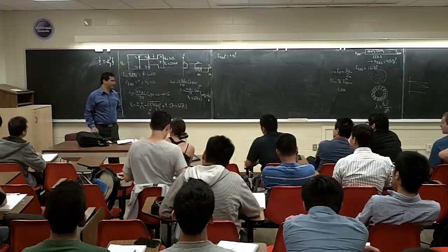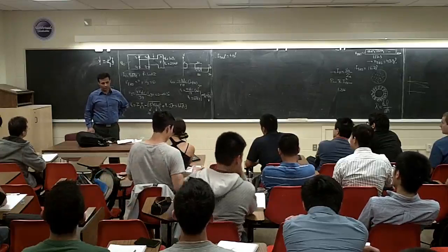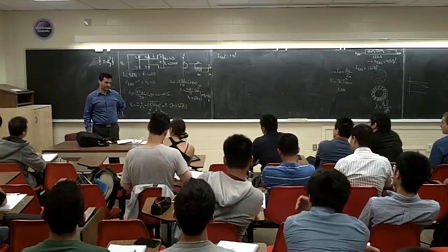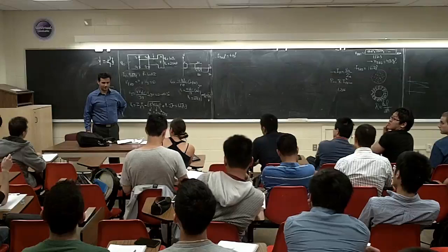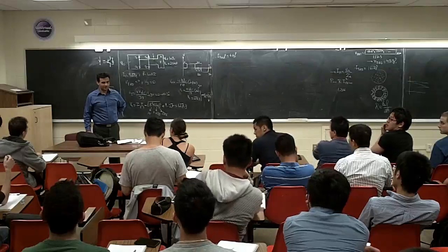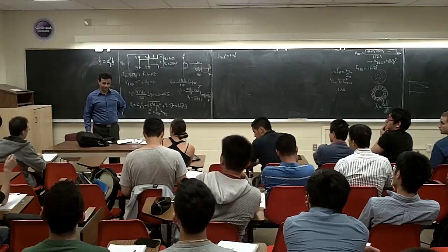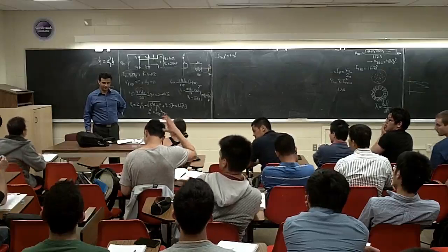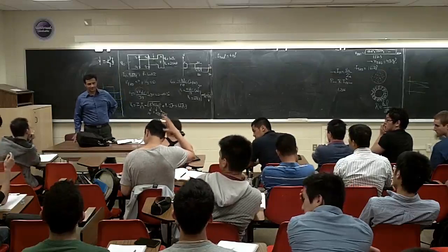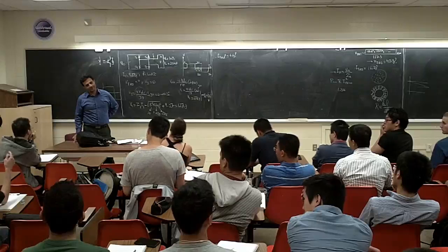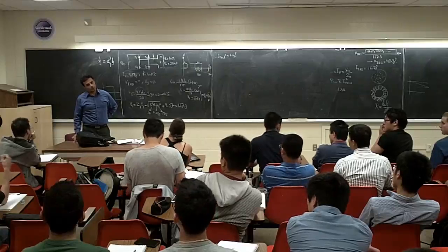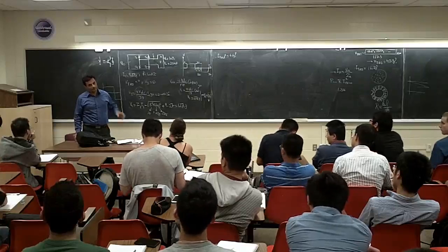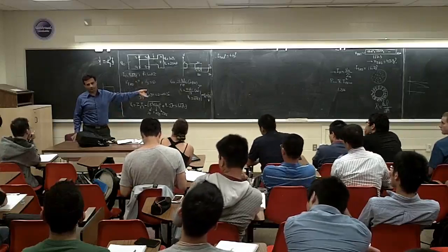So, if I'm going to get rid of the fifth harmonic, I should select a different alpha, right? Yes, but using this resulting signal, right? We use the same process again. But for the VDC, in the very first time we do it, we have to get a high VDC, right? No, but my point is, to get rid of the third harmonic, I have to have a 30 degree.